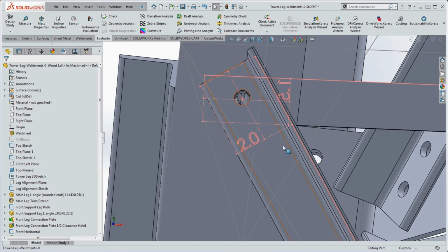So what do these blocks do? These blocks actually define how that path segment terminates. So if you look at the top up here, this block up here, every element in this block has got some sort of function in our model. Of course, this line defines the very end of our path segment line, which defines the very end of our structural member. This side over here defines the very edge of one of the wings of the structural member. And then this line over here, well, we've got the side, the front, and this other side over here. This line down here is a center line. It's a center line based on the back of our structural member, or the back of the wing of our structural member, and it just goes right down the middle here.